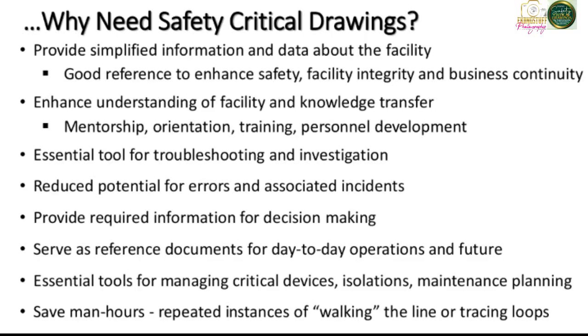Else, you may be making the wrong decision, and anytime you make a wrong decision, there's that potential that people may be exposed. Day-to-day operations require documentation, require drawings that you can make reference to. On a typical facility, people do isolations for maintenance, people do temporary defeats and a lot of other things. You need drawings to be able to ensure that the decisions you are making on a day-to-day basis on the facility are the right ones.